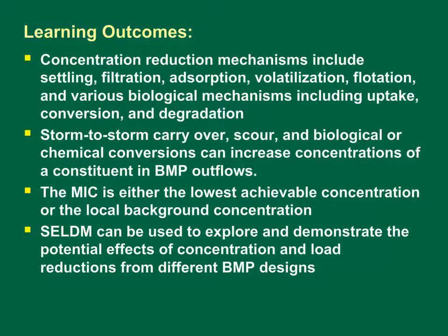In this training module, we learn that concentration reduction mechanisms include settling, filtration, adsorption, volatilization, flotation, and various biological mechanisms including uptake, conversion, and degradation. Storm-to-storm carryover, scour, and biological or chemical conversions can increase concentrations of a constituent in BMP outflows. The minimum irreducible concentration is either the lowest achievable concentration or the local background concentration. And SELDM can be used to explore and demonstrate the potential effects of concentration and load reductions from different BMP designs.